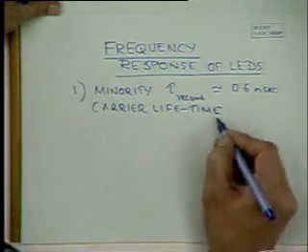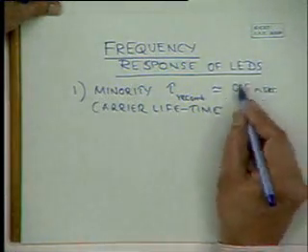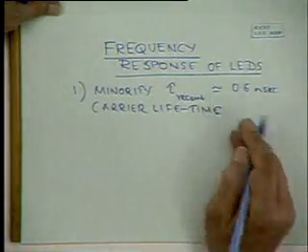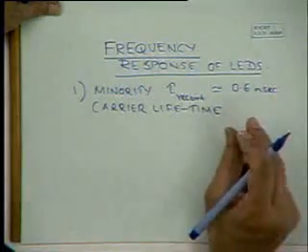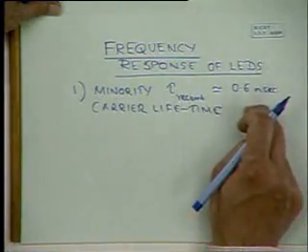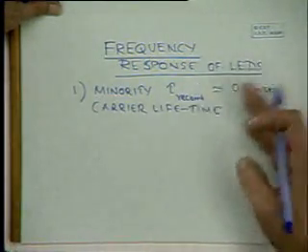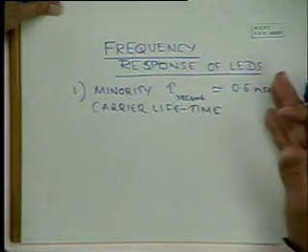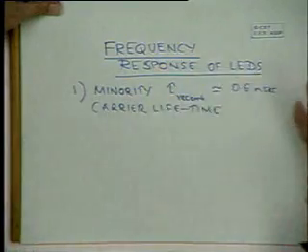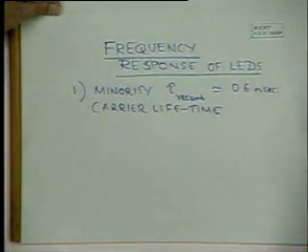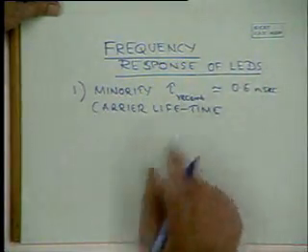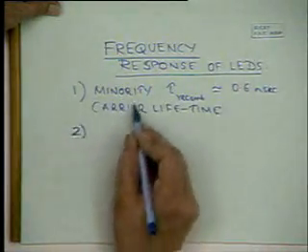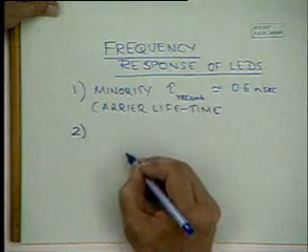Suppose you are injecting carriers, they live an average of about 0.6 nanoseconds, say 1 nanosecond. Suppose the input signal is faster than this, then obviously the carriers cannot keep up, and the response will decrease because the carriers are not able to recombine and give rise to light. So that is one factor, which I'll go back to and we'll do a little calculation.